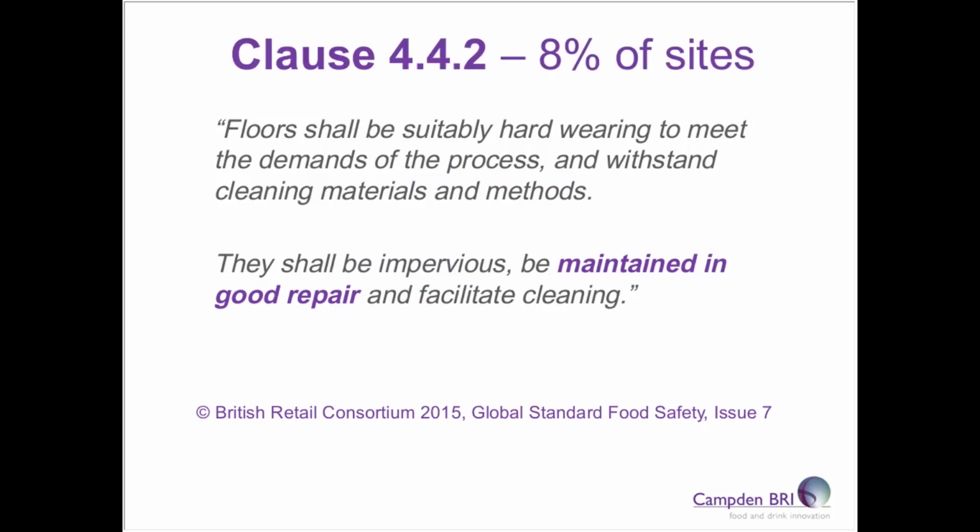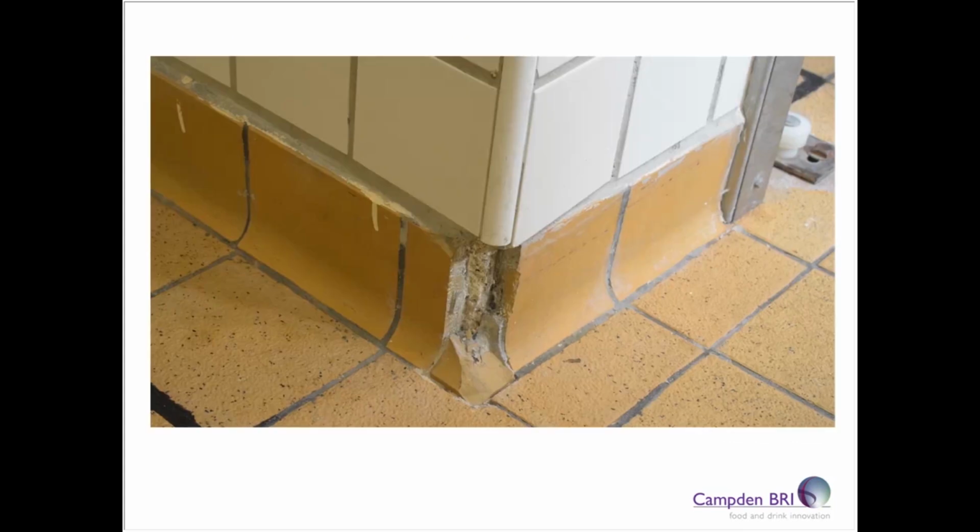The next non-conformity, or the next clause of non-conformity, is 4.4.2, and 8% of sites have an issue here. Floors should be suitably hard-wearing to meet the demands of the process and withstand cleaning materials and methods. They should be impervious and be maintained in good repair and facilitate cleaning. The example shows some just poor maintenance on the behalf of the floor